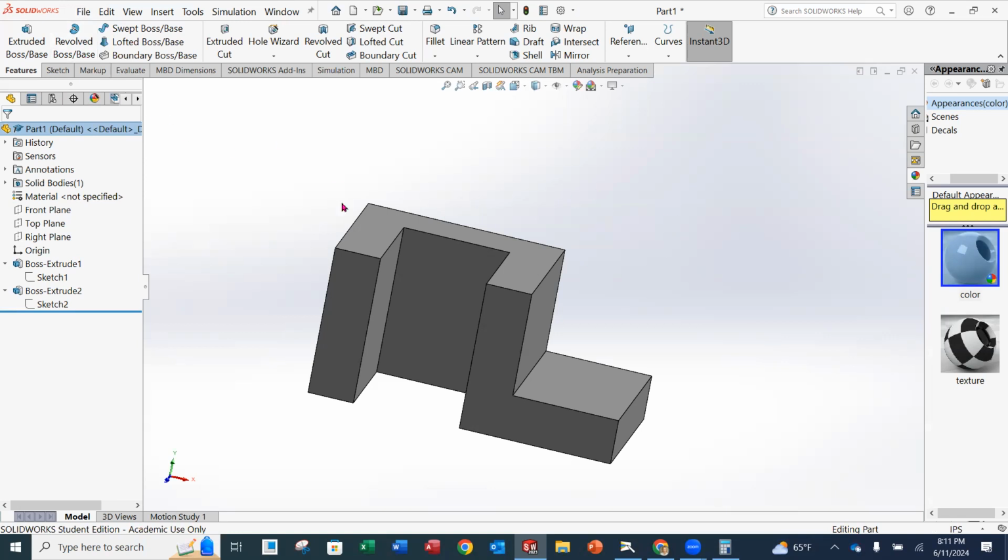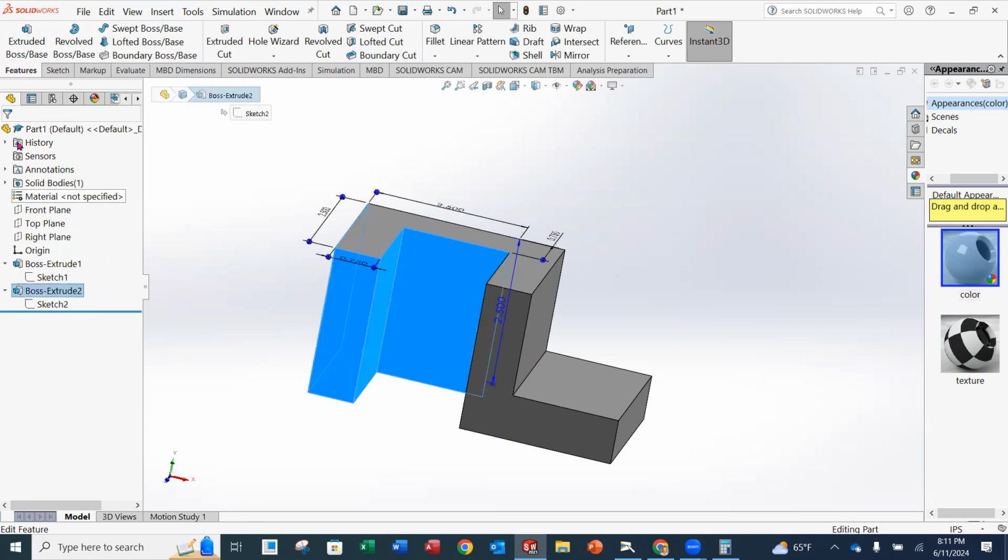It stayed the same. Okay. So if you go on to your sketch number 2, you go up to Extrude, and hit the extrude feature. It's going to be under Features and then Extrude. Did you do that? Okay.